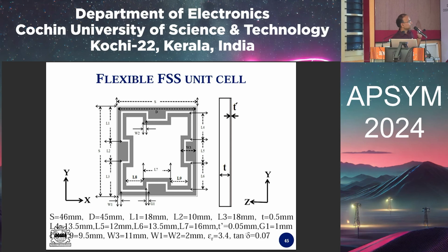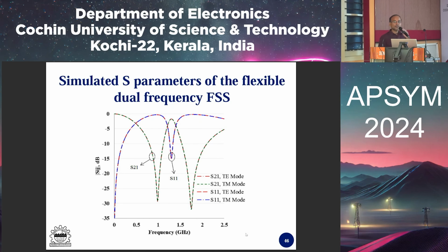So in that pursuit we have designed this FSS based on a flexible unit cell. That consists of two concentric square elements where we have some kind of convolutions. The reason why we go for convolution is to accommodate low frequencies in a smaller unit cell. So the electrical length can be much higher, but we need to make sure that the physical length is much lesser so that we can make the FSS suitable for all angular incidence, or angular independency.